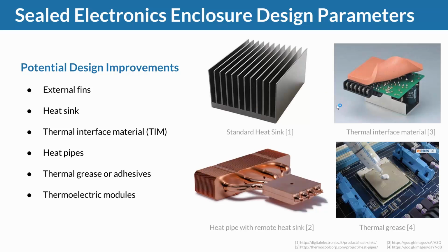And a couple of examples can be shown on this slide. Obviously, even in sealed enclosures, there might be an improvement to the thermal performance when we put heat sinks in there. And actually, we're going to see an example later today where that will work. There are all sorts of thermal interface materials, TIMs, different heat pipes, or different adhesives that I can put on the semiconductors. But what's not on this slide, and I think that's more important, is fans. We cannot put something in there that just blows more air over the semiconductors that get hot.